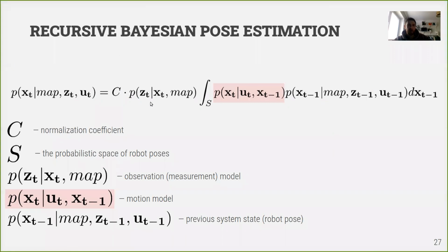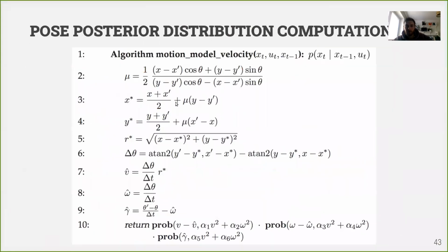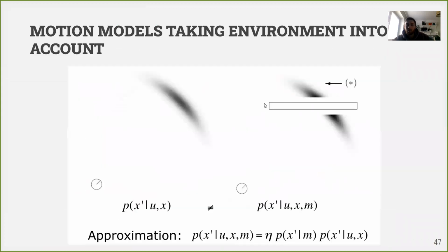And this gives us a lot because on the further steps, when we use our correction step with a motion model, we will not have to work with part of distribution which is improbable. Otherwise, we would have for each hypothesis, or each probable pose of the robot, to correct the pose with measurements of sensors. But excluding part of distribution just simplifies our tasks, because this part of distribution is improbable and we can exclude it beforehand, which is quite good.